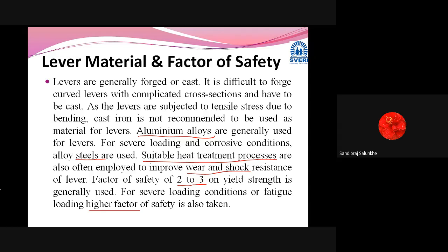Now we are surrounded by the sugarcane factories, or sugar factories. So all the boilers which are there in sugar factories, they can only run when they are getting certificate from the boiler inspector. The boiler inspector checks the safety valve, whether it is going to operate or not. He is going to check all the mountings, and then afterwards he is going to give the recommendation for starting of that boiler.